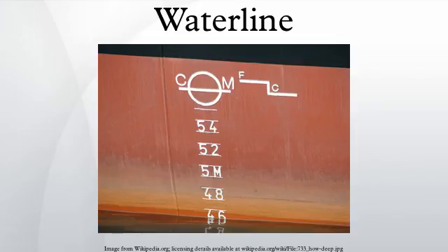that may arise. Temperature affects the level, because warm water provides less buoyancy, being less dense than cold water, as does salinity, because fresh water is less dense than seawater. For vessels with displacement hulls, the hull speed is determined by, among other things, the waterline length. In a sailing boat, the waterline length can change significantly as the boat heels, and can dynamically affect the speed